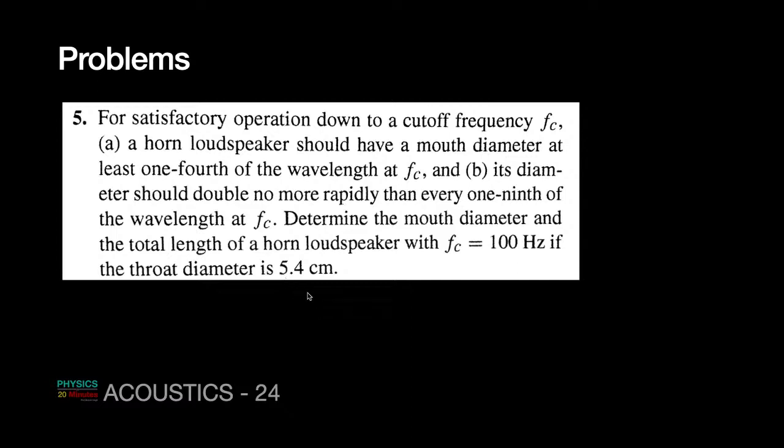So if you move on the axis by 0.4 meter, that is around 40 centimeter, then 5.4 should become around 10.8 centimeter. You can mark these points, and that is how the cone can be designed. So this is how the design considerations of the horn loudspeaker can be placed, and you can get a design.